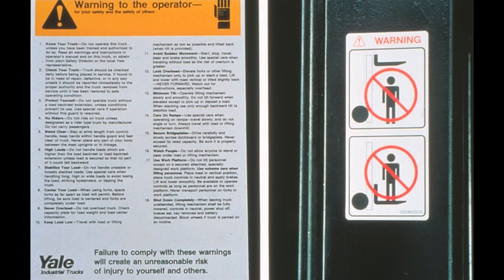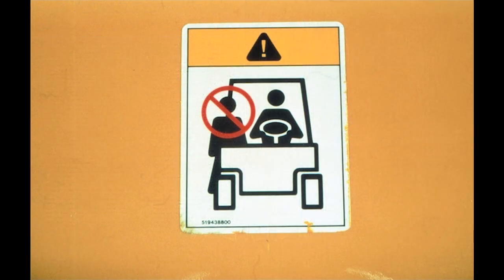Here is a reminder of some safety rules to follow when operating a lift truck. You should become familiar with them from this training and from reading the operator's manual. Don't ever let anyone walk under or near your forks when they are raised. Items falling from a rack or load can easily cause personal injury. Never let anyone ride on the forks, and never allow anyone, including yourself, to reach through the mast. Moving mast parts will remove a hand or limb. Never let anyone ride with you, or allow an unauthorized person to drive your truck.